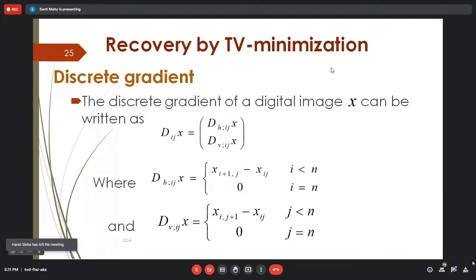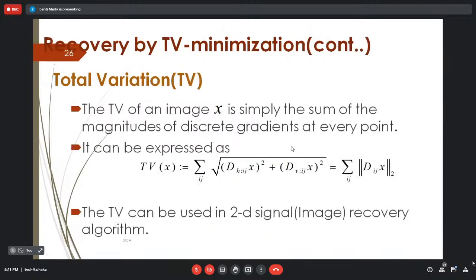So when you apply an operator over an image signal, you are looking for a filter or kernel whose coefficients give rise to a derivative operator. So this is basically your Gx. Suppose you have a pixel, this one and this one. Horizontally you take the difference, that's your delta X. When you take the vertical difference, that's your vertical edge, dy. And now if you take the square root of gx squared plus gy squared, you have a simple way of calculating the edge.